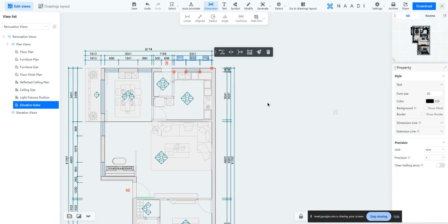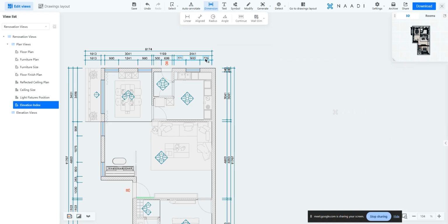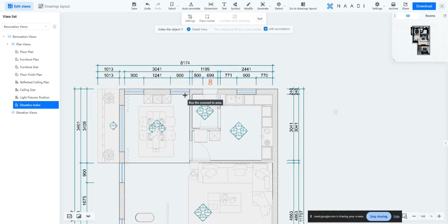Okay. At the initial phases, you can just manually select, but once you're familiar with the process, start focusing on your shortcuts as well. So that way, any common tool here, you will have a shortcut defined for it. Like I said, place your cursor, it will tell you what the shortcut for that region is. So that way, the shortcut for your call out is Shift D. Just click it, and now you can just place the call out here.